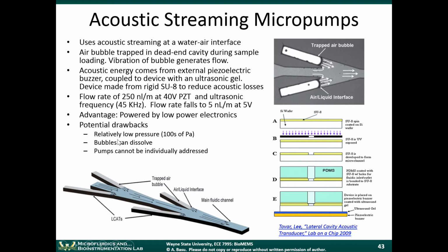The potential drawbacks of this technique are that it's relatively low pressure. This type of acoustic streaming can provide flow rate only if you don't have too much back pressure in the system. Secondly, the bubbles can dissolve, and pumps cannot be individually addressed. Those are all some potential drawbacks, but still it's a very nice technology that you can get a pump just by vibrating the entire system.